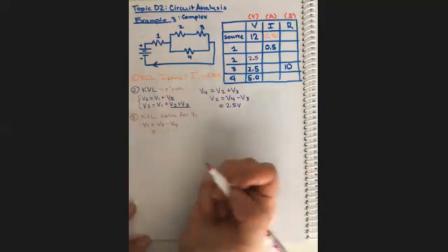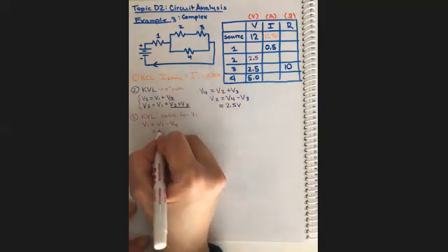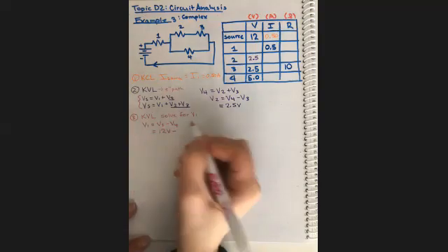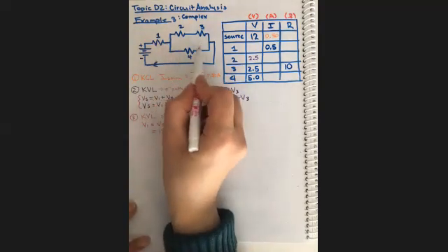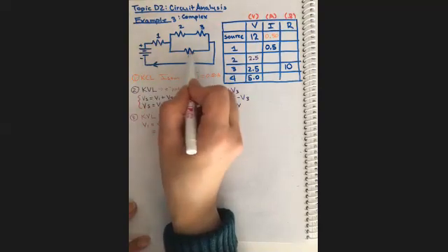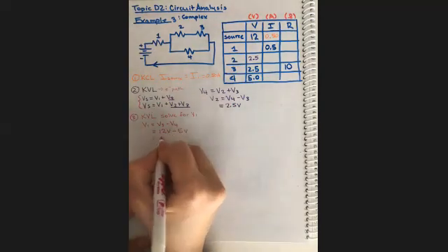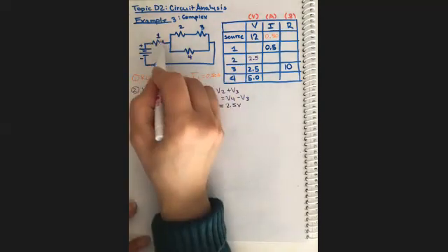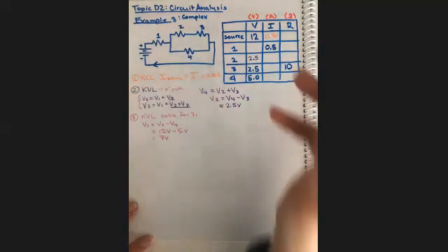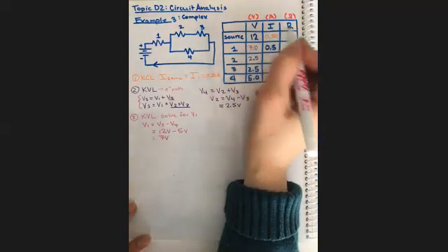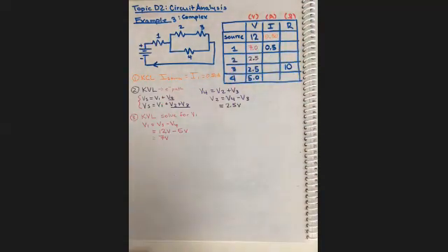Vs, as in the voltage gain across the power source, is 12 volts. Subtract, if the electron chooses that path, some of that 12 volts is dropped at V4, which is 5 volts, and then there's 7 volts left that would have to be dropped off at V1. So we've got 7.0 volts for that one there. As the problems get more complicated, you have to have a wider range of colors. Okay, so now what is a good step?